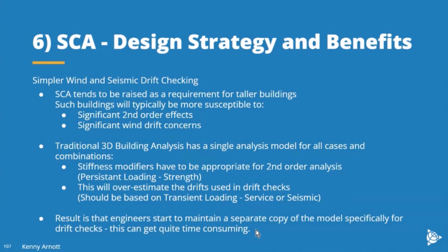What we've seen some proportion of engineers do is maintain a separate copy of the model. They've got one copy of the model for the design, and then a separate copy where they use adjusted stiffness modifiers specifically for the drift checks. Establishing that takes a little time, but maintaining it, if you're working through the evolution of a design, and constantly changing two models or re-establishing one model from the other, becomes time consuming and potentially a little error prone.